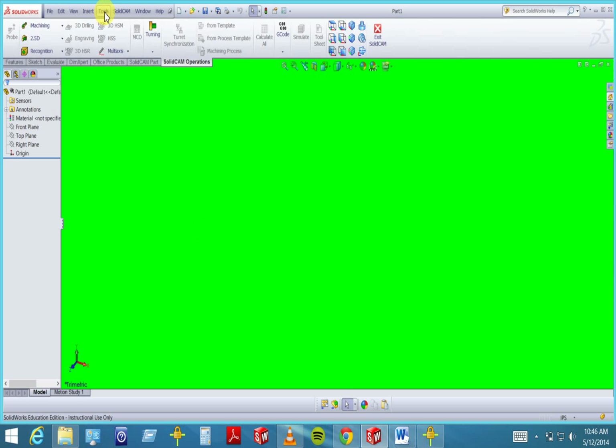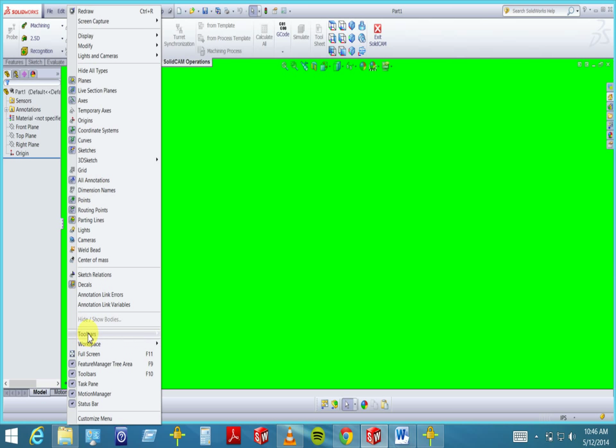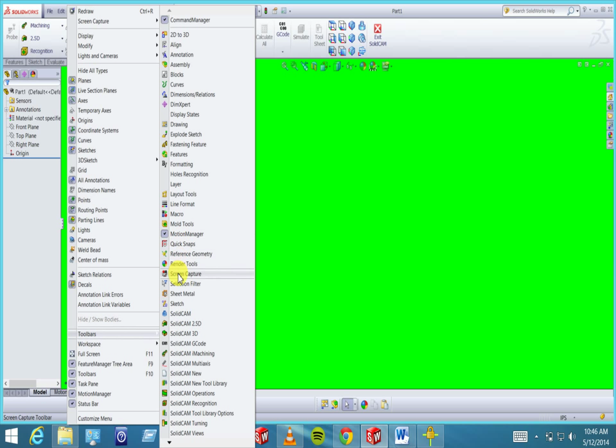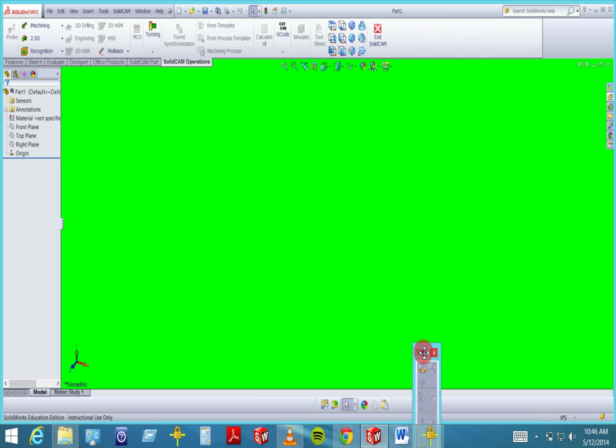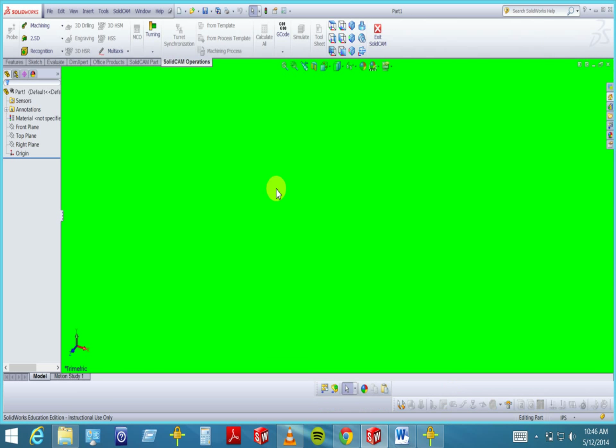I also believe that your toolbars affect your template. I'm not sure about that, but you could check it out. I think if you put in a toolbar, let's go back to that sheet metal toolbar, and I dock it down here. Let's say. I believe if I save this as a template, that toolbar will always come up. Okay, so that's a nice thing to have also.